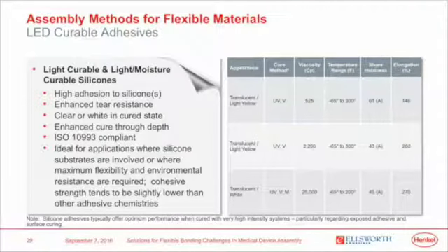I will just make a note here, and you'll see the footnote on the bottom of this slide, that although the silicones can be cured with LEDs, if there are exposed adhesive joints or there's a surface curing application, there are cases where they may require either a stronger LED or a more traditional high-intensity system in order to facilitate curing of exposed adhesive.